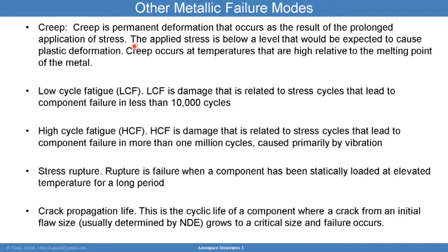So anyway, creep can happen, and usually it's one of those failure modes that is ignored. And I invite you to really pay attention to that particular failure mode because it is ignored. And it is ignored often. And I'll be paying attention to that today with examples I'll be providing because it is a painful failure mode that gets often forgotten, and it has caused some massive failures.